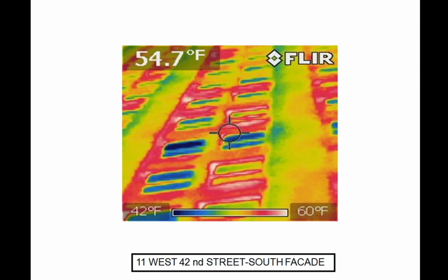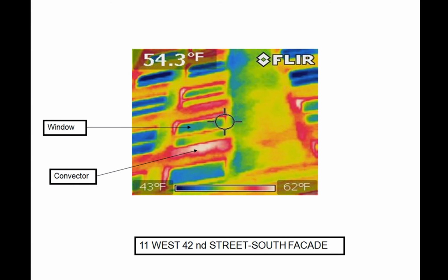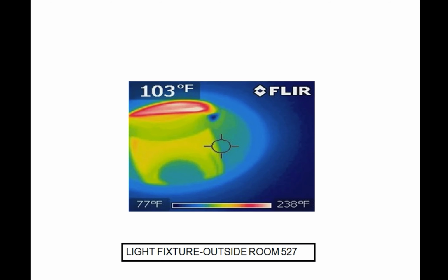So here's an example of that thermal imaging. Thermal imaging is often used to figure out where you're getting heat losses in a building, if there are any issues with the facade, where you might have poor seals within the facade. Blue is generally cooler and red is generally hotter. As you're going through, you can see the outline of a window. You can see where heat is generated, through heat pumps or convection. So you probably have a heater line along that wall there. And again, something like a light fixture, the bulb itself will be radiating heat, while the fixture around it will be fairly cool.